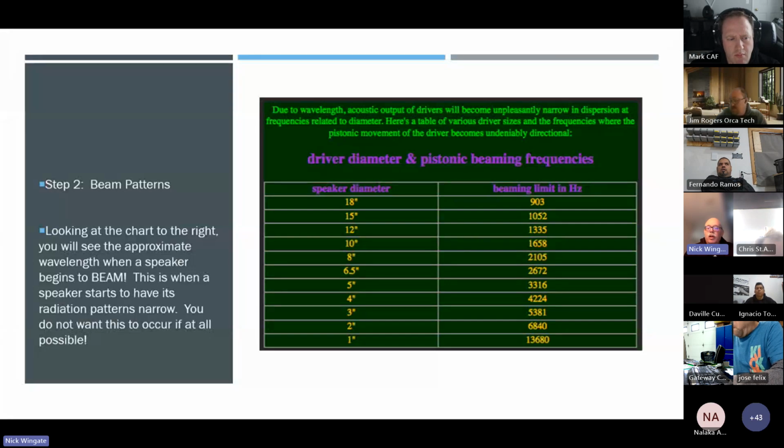It doesn't sound very good. That's because the speaker on the top of the dash probably isn't playing down to 2,600 hertz. Most of the tweeters that are small enough to fit up there don't play that low. That's the reason why, because the 6.5, it starts to fire straight across the car, okay?